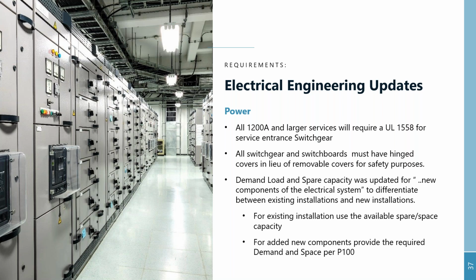If your project is in an existing building, you make use of whatever has been provided as demand load, space, and spare capacity. You don't have to maintain that for existing equipment. But if you are adding new equipment, panelboard, switchgear, or motor control center, those requirements on demand, spare, and space capacity have to be followed. It's a must.